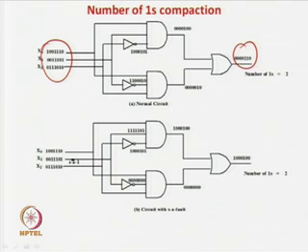And here if you find out this value, there will be 2 ones in this case, because this is an OR gate, so this is one instance and this is another instance. So, in the 2 instances the output will be 1. So, the number of ones in this case is equal to 2. Now, let us take a case where there is a stuck-at-1 fault over here. Stuck-at-1 here means that every time it will be all ones.